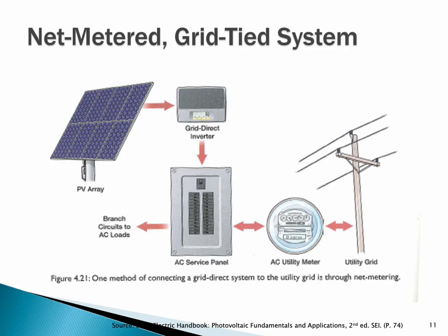In a net metering scenario, this is a single bidirectional meter that has to be set up by the utility. This is a special meter. If it's a digital one, more of a smart meter like we have in ComEd territory, or most of ComEd, you would see that taken care of from their HQ. Nobody comes out.